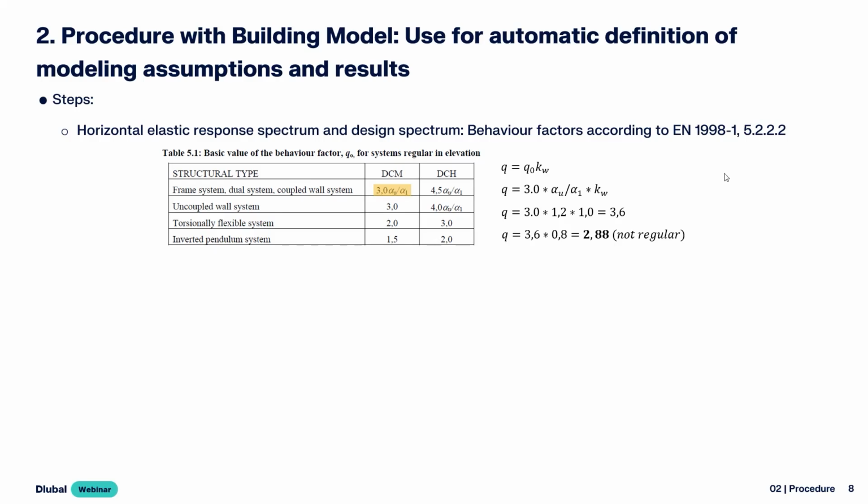And in this case, for our concrete structure, I made a definition. Yeah. How this works is that according to the location and according to the norm for a particular country, it is defined which ductility class or which kind of requirements I have to fulfill for this particular place. For example, in Italy, high seismicity, I have to select a structure that fulfills particular requirements.